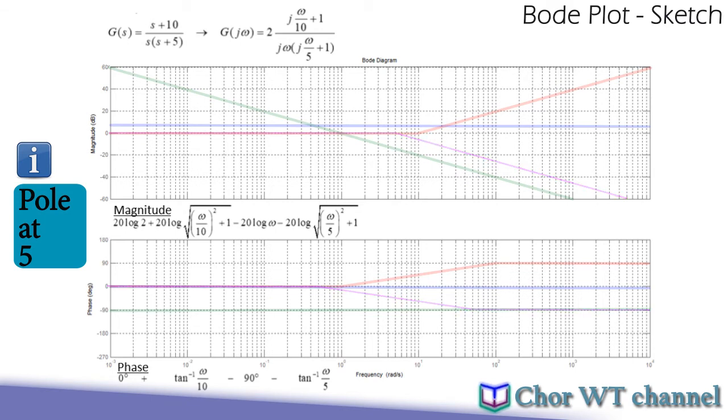Okay, these sketches will describe the individual subplots of the Bode plot, but we still need one complete plot that describes the Bode plot of the entire system. So what we need to do is just to graphically sum all the points together. So let's look at the magnitude plot. We can take one reference point where the frequency is equal to 1, and at the frequency equal to 1, the magnitude will be 6 dB.